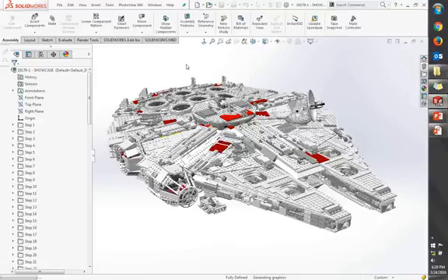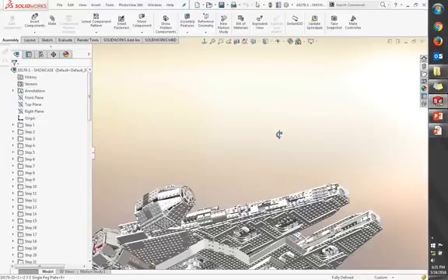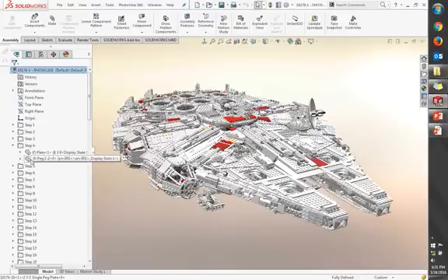So it's fully loaded now. If I take a look at any of my folders here, you can see that the parts are loaded full weight. There's no lightweight parts being loaded up in here. So like I said, in review, 5,600 parts, 17,000 mates. I just got the assembly to open up in about 44 seconds. I have a solid state drive. When I had a spinning drive 2 years ago in 2014, this was at about 1 minute and 15 seconds to open up. So it did increase my speed, but it's not that it increased it tenfold or anything like that.